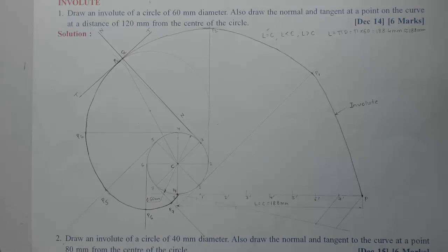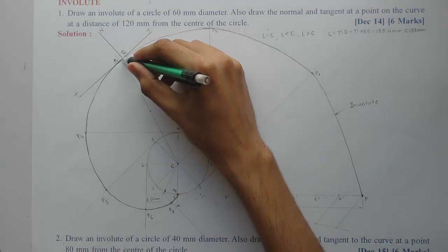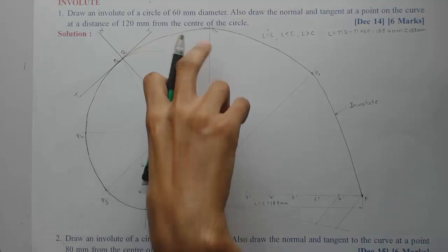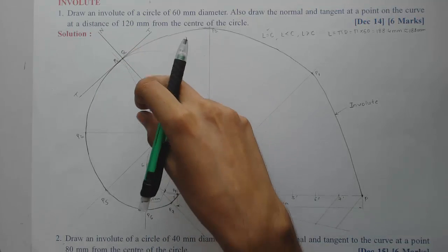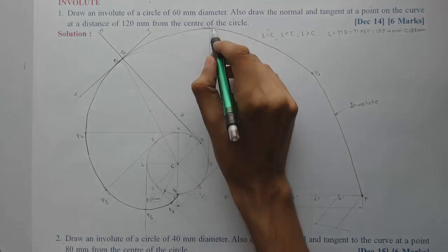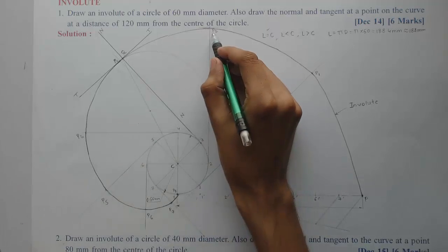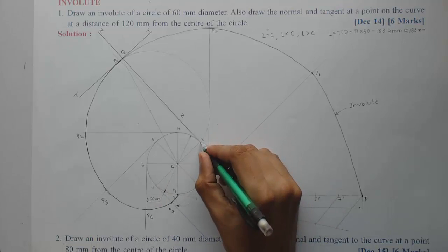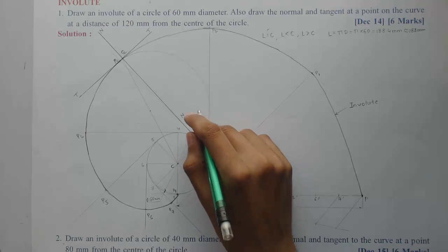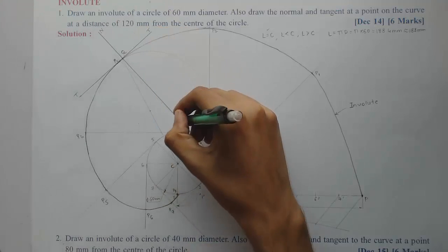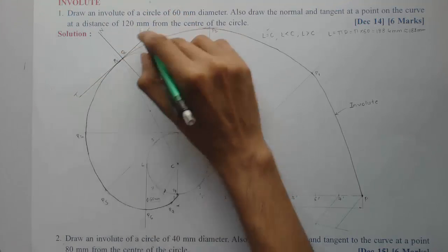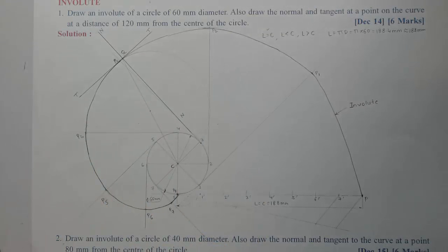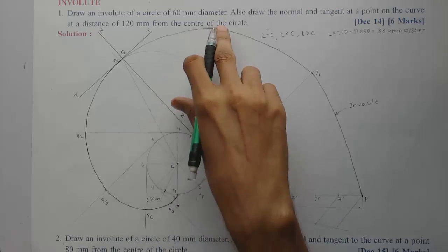So for drawing the tangent and normal, the procedure is first locate the point where you want to draw the normal and tangent, then join that point with the center of the circle, then with that length as a diameter draw a semicircle. But be careful while drawing the semicircle, we need to draw the semicircle on that side where the point Q is lying. It is lying between 2 and 3, so I need to draw the semicircle such that it will give me the intersection with the original circle between 2 and 3. So that intersection point here, after joining with Q, will give me the normal, that will be denoted as NQN, and drawing the perpendicular to that normal at point Q will give me the tangent. So we have drawn the normal and tangent. So this completes the solution for this particular problem.